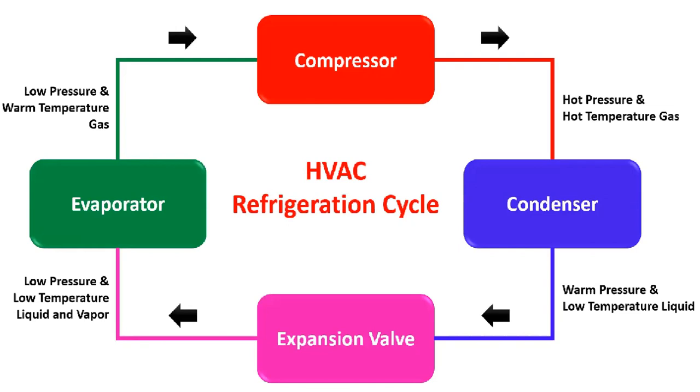There are several heat transfer loops in the refrigeration system as described. As we see in the figure, thermal energy moves from the left to the right as it is extracted from the space and expelled to the outdoors through the 5 loops of heat transfer. We see the compressor, condenser, expansion valve and evaporator, the 4 very important elements.